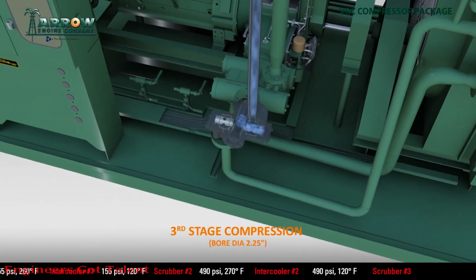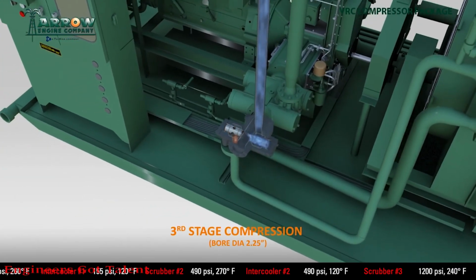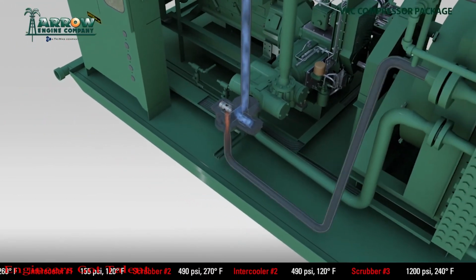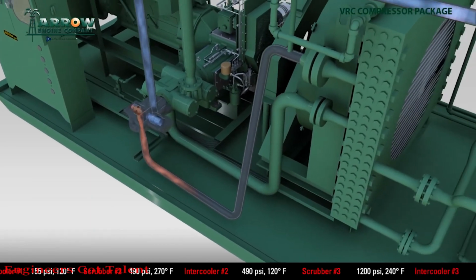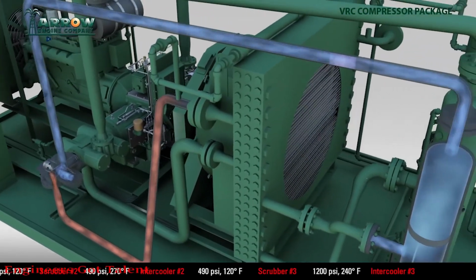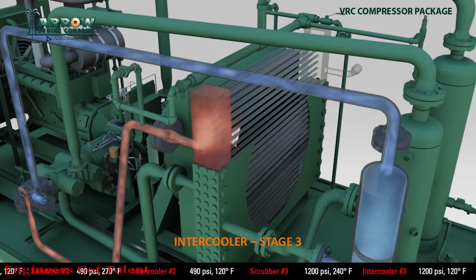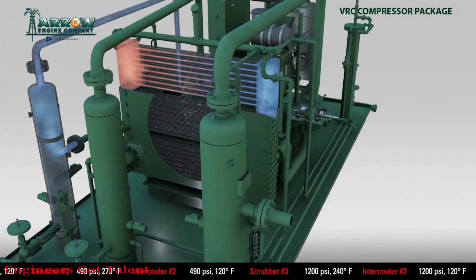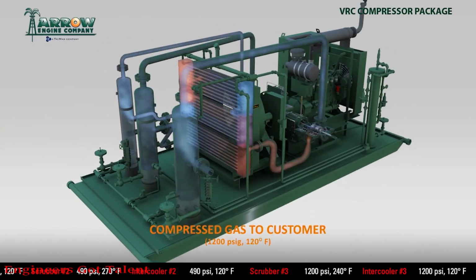The third stage of compression gets the pressure up to 1200 psi and 240 degrees. Once again, the hot gas will go through the cooler and exit at the discharge at 120 degrees. Some producers will run the gas through one last scrubber to give any remaining liquids a place to drop out.